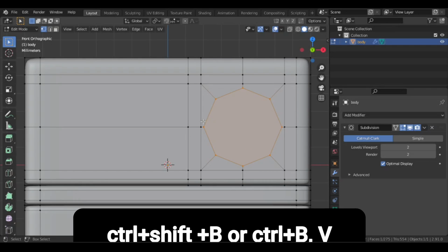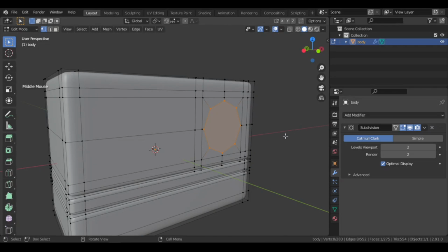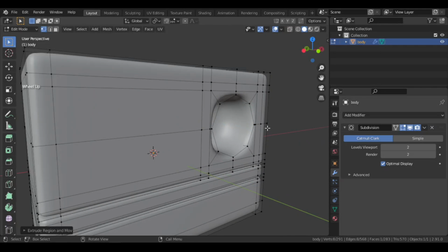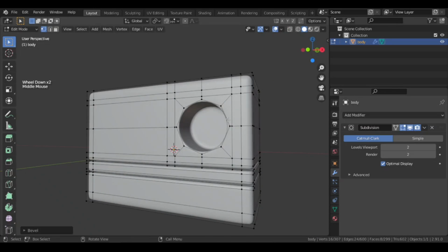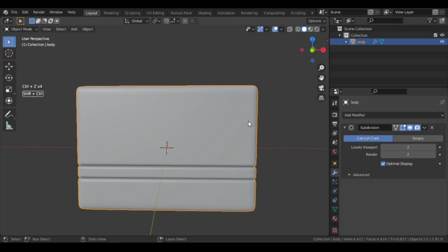Furthermore, you can also join these vertices, and these two vertices, if you want every face of your model to be quads. Now you can simply extrude this inside, and left-click to confirm the position. But since this is giving some shading issues, you can add a loop cut in the middle, and then bevel that loop to tighten the edges. But you know that already. So undo it, and let's look at a slightly different way to do the same.